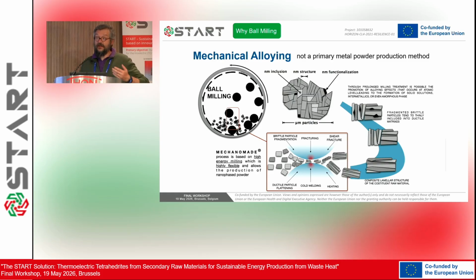After a certain repetition of these events, you start having one material folded into another to disperse oxides or brittle materials in soft matrices, and in general to create a quite specific nanostructure that improves the materials. In most cases, it improves the mechanical properties of the materials.